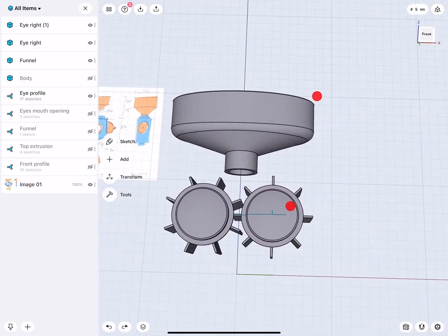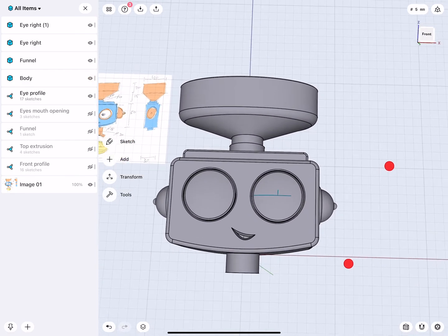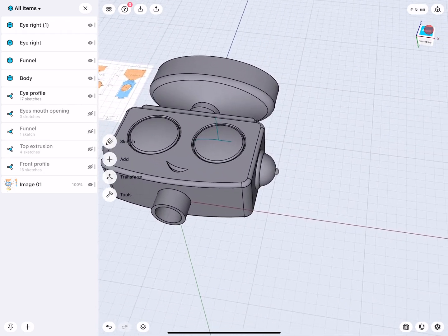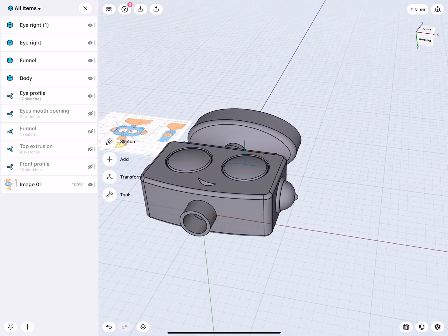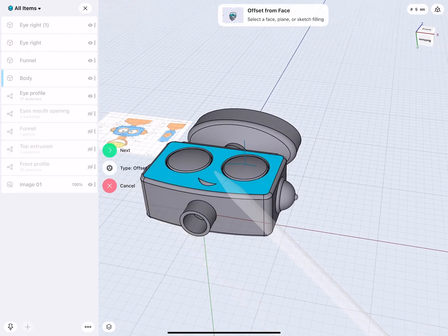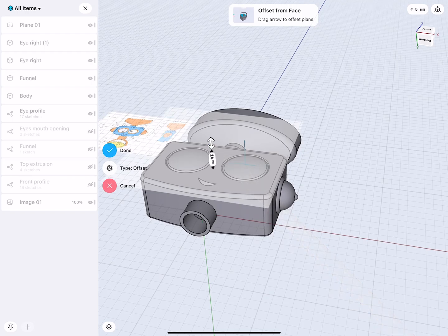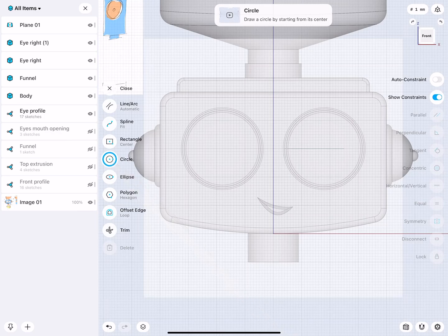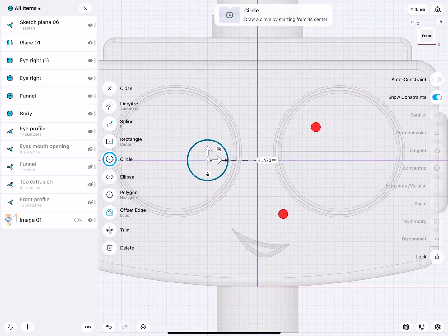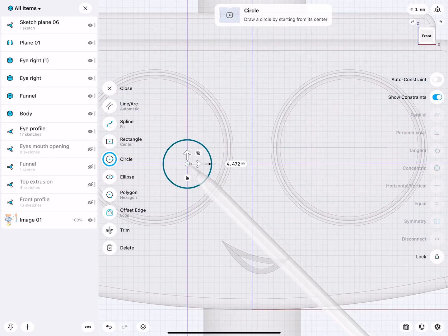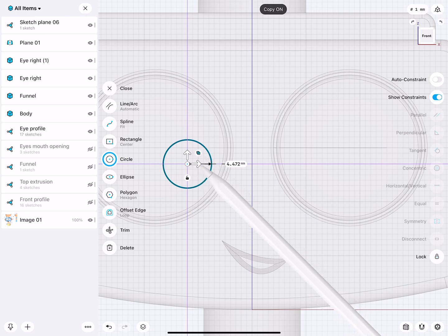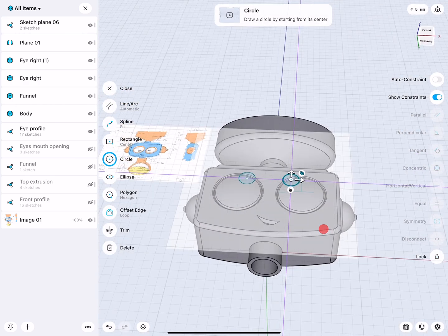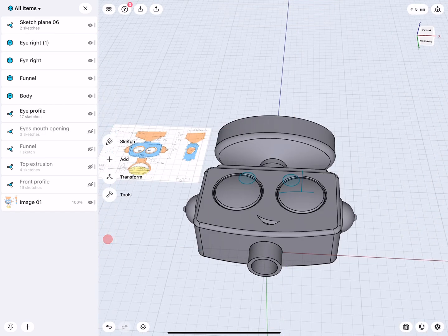So it looks nearly complete. Before we can add colors, we need to add something for the eyes. So how do we do the eyes? It's actually easy. Add construction plane from this flat surface. We simply add a plane up. On this plane, double tap, and then let's create the eye detail. So there, copy, simply move this over, and via the grid, I line this up. There we are. This construction plane I delete.